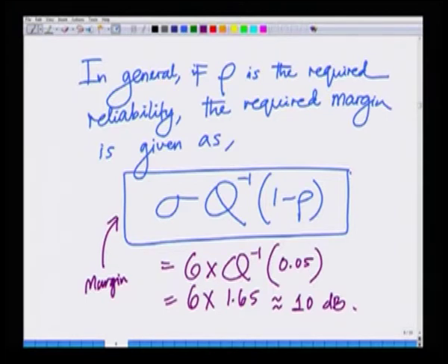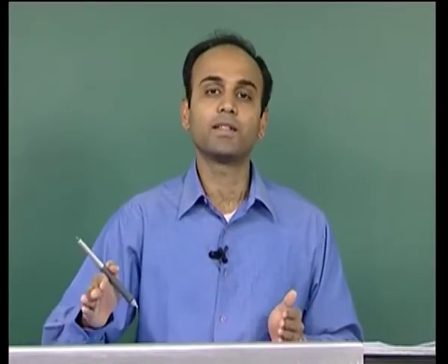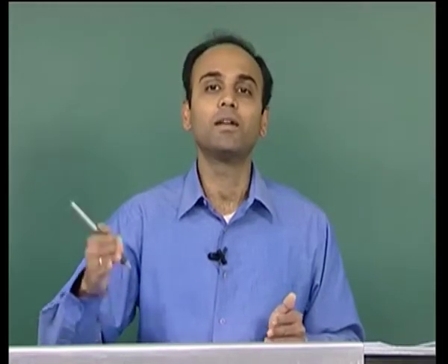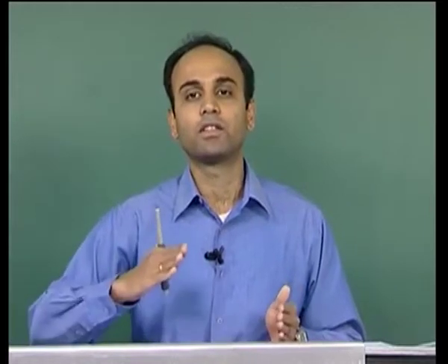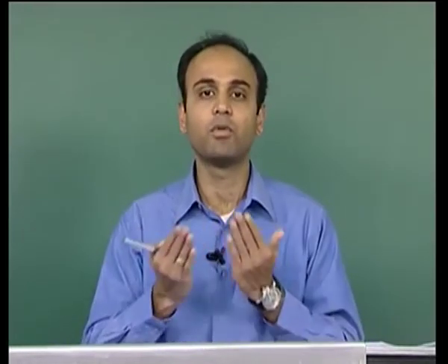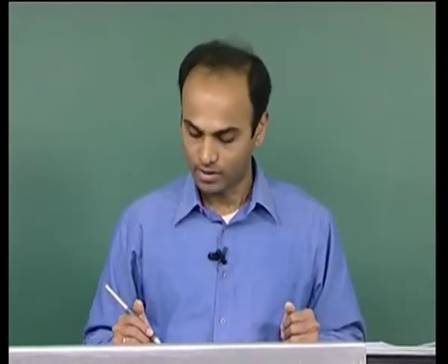So, you can think of it two ways. You can either think of it as path loss greater than a certain threshold, or path loss lower than that threshold with probability 1 minus that probability, which is nothing but the reliability. One is outage, which is the path loss being greater than the threshold. The other is reliability, which means the path loss is lesser than that threshold, and the sum of both these probabilities is 1 essentially. Okay.